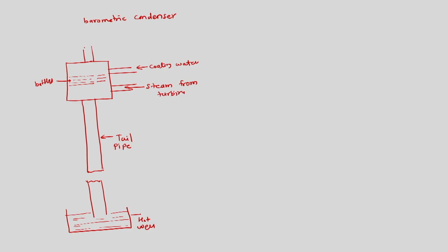and then there will be some non-condensate. So the cooling water would come out, it will get splashed, and then it would mix with the steam, and the steam will get condensed in this process, and then the mixture will come down and get settled in the well.